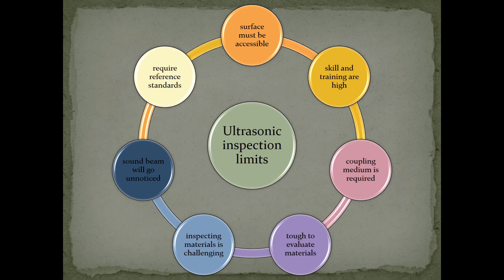Ultrasonic inspection has its limits. To transmit ultrasound, the surface must be accessible. The level of skill and training is higher than with some other approaches. To facilitate the transmission of sound energy into the test specimen, a coupling medium is usually required.